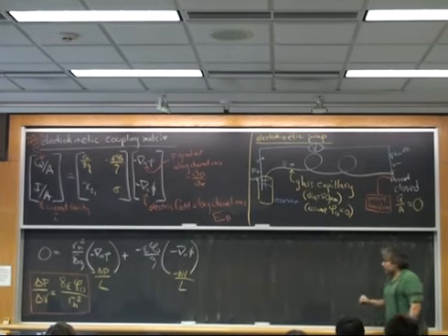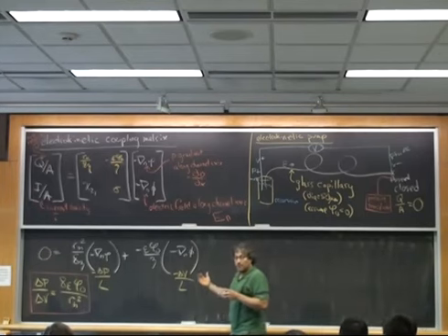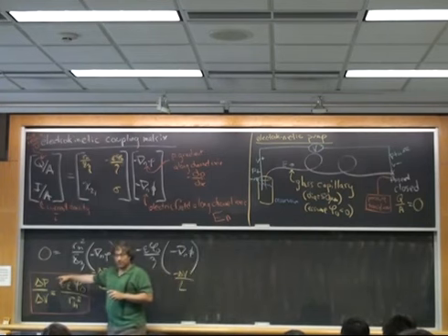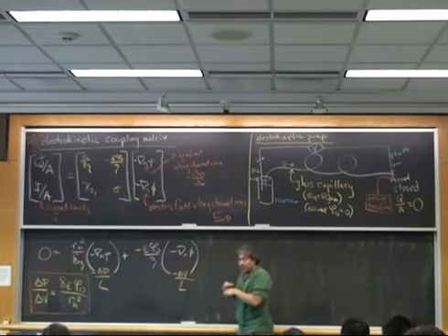Not any more than someone at one end going and blowing on it can cancel out, right? So if you look at the flow rate of electroosmotic flow, it gets bigger and bigger as the tube gets large. But who cares? Because the flow rate associated with pressure is going up by the characteristic length to the fourth power, right? I go down to something smaller and smaller and smaller. Yeah, my flow rates are going down.